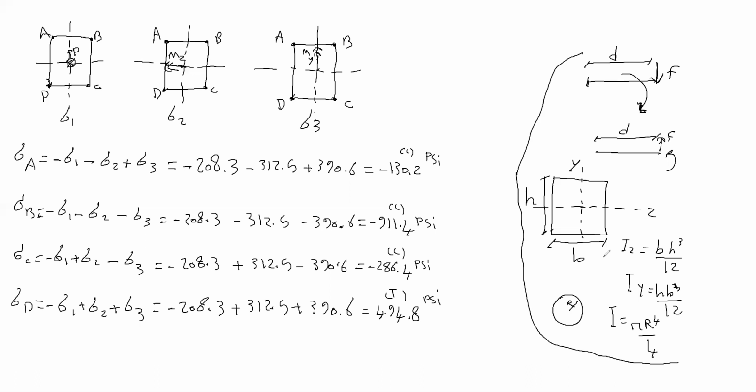We don't have stress at that point or at that line, right? In the previous example that was easy to find because we have only one moment. We know the top is positive, the bottom is negative, and then we use a similar triangle. Here, the problem is we have 2 moments, right?